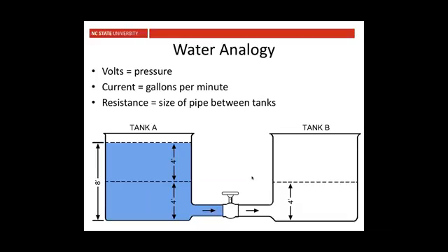So when you pick a wire, it's going to say 300 volt wire, 600 volt wire, 2000 volt wire. That's a voltage rating that's printed on every piece of wire that you buy, because that plastic insulation has to be strong enough to withstand the pressure that you're exerting inside the conductor from the voltage on the system.